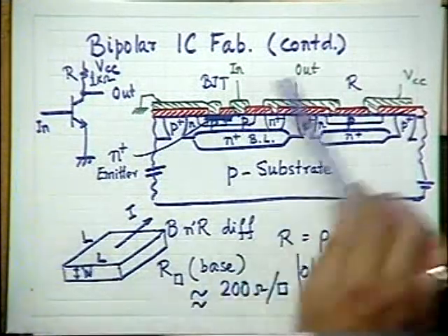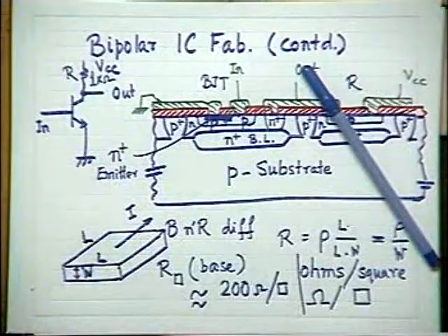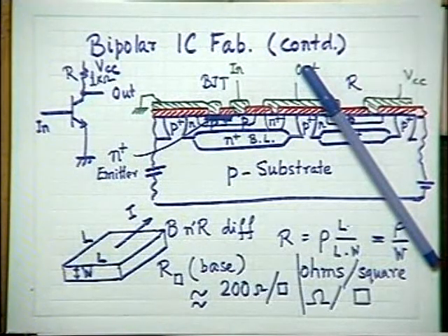The pinched base region, this is what is called pinched base. The pinched base region, because it is extremely narrow, will provide a very high resistance. And this is what is called a pinched base resistor. Resistances of the order of hundreds of kilo ohms can be easily realized using these pinched base combinations. But they again suffer from a very high TCR.